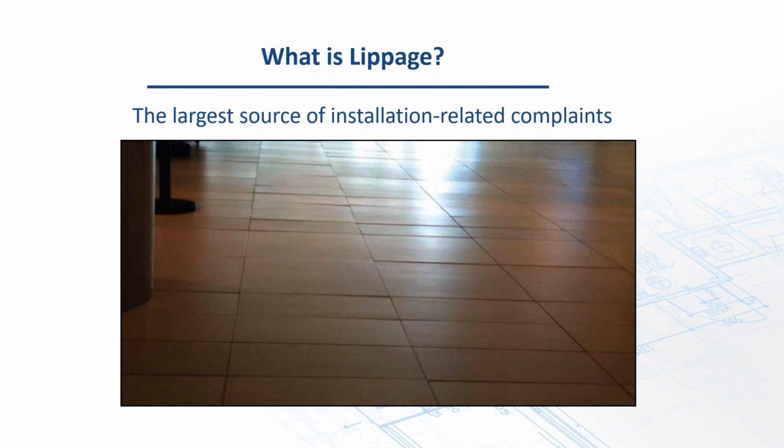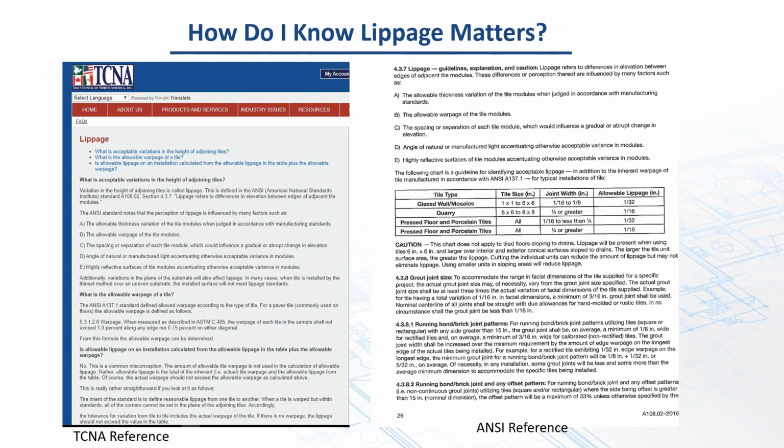Well, why is lippage such a big concern? It is by far the largest complaint in installations, whether it's floors, walls, or anywhere. It's just not attractive. What do our industry documents say? The TCA reference manual has quite a bit on it, on the TCA website as well as in the handbook on lippage. ANSI, as I said, has it in there in the A108.02.